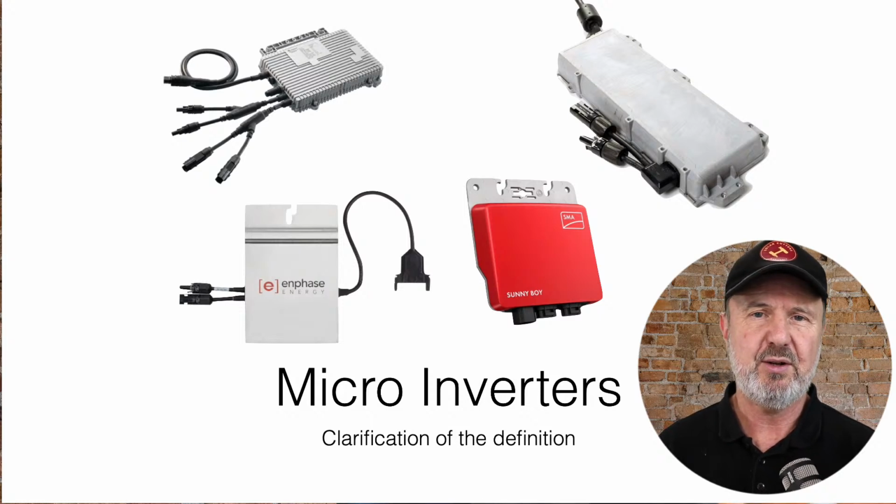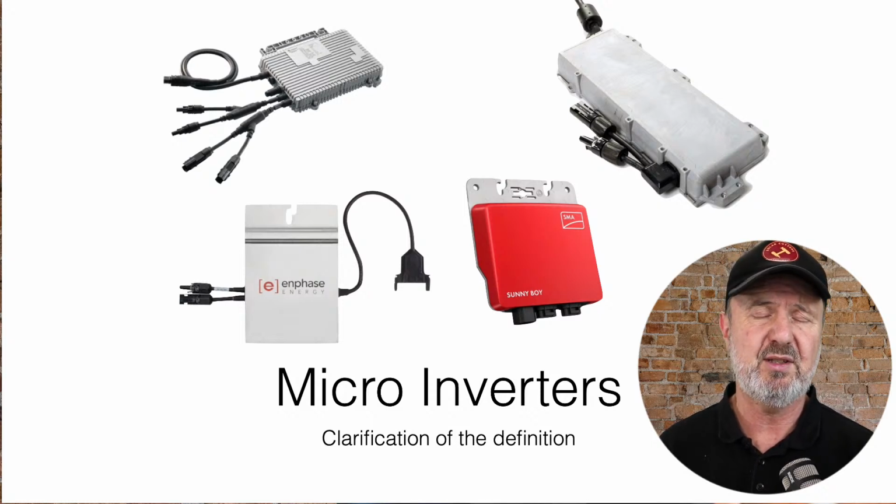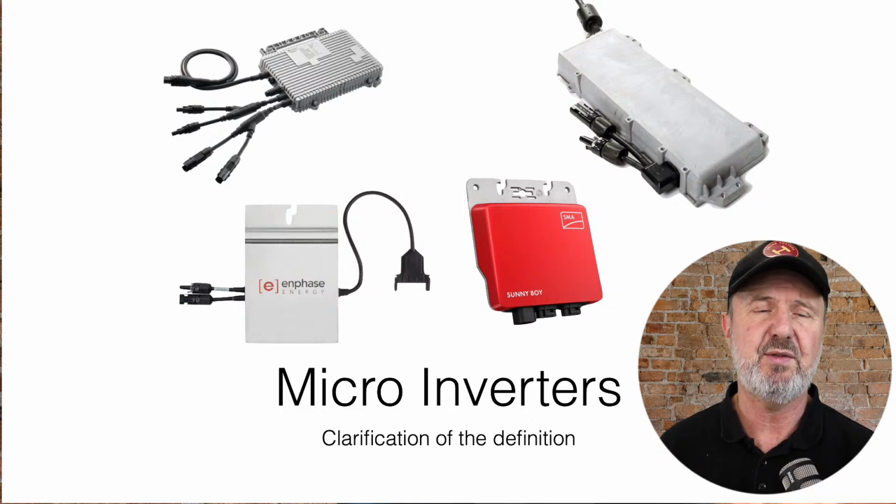The advantages of microinverters, therefore, is safety. You've only got an AC network on the roof, so that your normal overcurrent protection systems in the home will protect that circuit. You don't have the risk of arcing that you can get with DC at higher voltages. They give you the same benefit of optimization at a module level and monitoring. So both microinverters and DCUs or optimizers generally will give you a monitoring solution as well that allows you to see the performance of every panel.